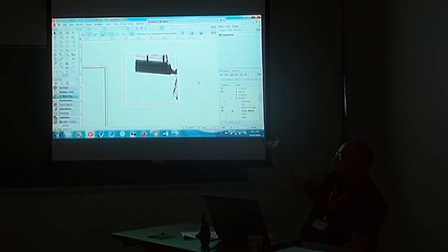What I'll tend to do, like when I started modeling all this Jurassic Park stuff, was I created one class initially, Jurassic dash main or whatever it was, and I just started putting all my objects on that. Then as I progressed, it's like, okay, here's the fence, here's the base of the fence. Then I would just copy that class and reassign, this is now fence base, this is now fence. So I start with a class that's for everything to do with Jurassic Park or everything to do with Avenue Q, whatever, and then I just make copies of it and rename them as I go.